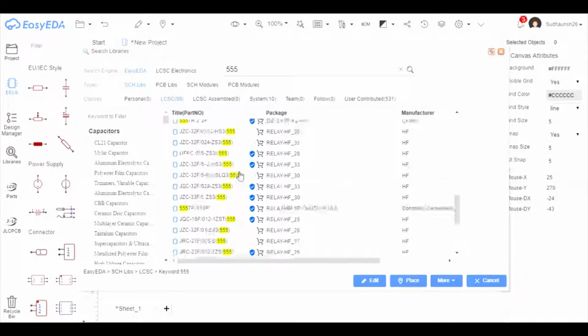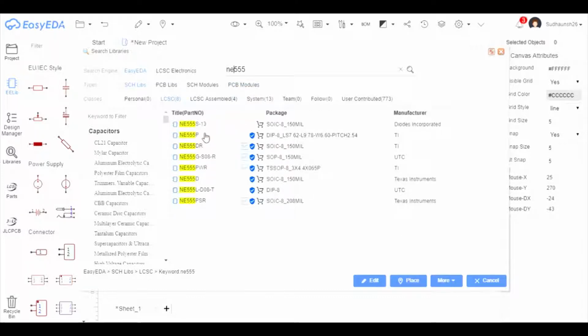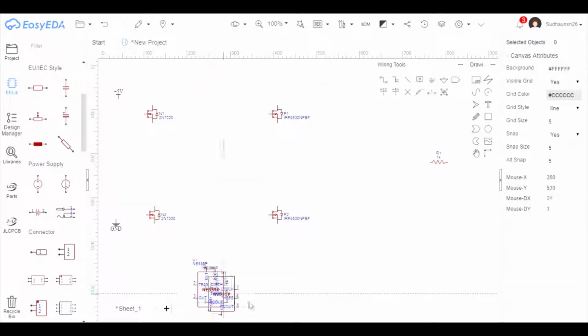I'm not creating any peripheral circuit right now. Let it just be the output, since I just want a 60 Hz signal, and that is what you basically want because of switching. So you want a 60 Hz square wave, AC square wave. Let's connect this 60 Hz signal to each and every gate of the MOSFET, all the MOSFETs.